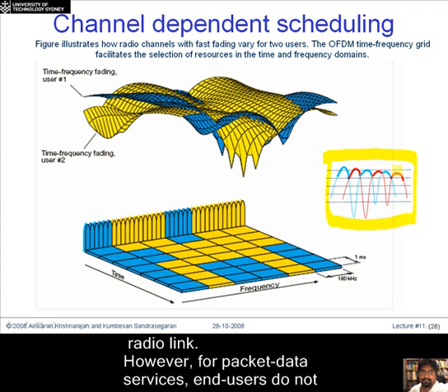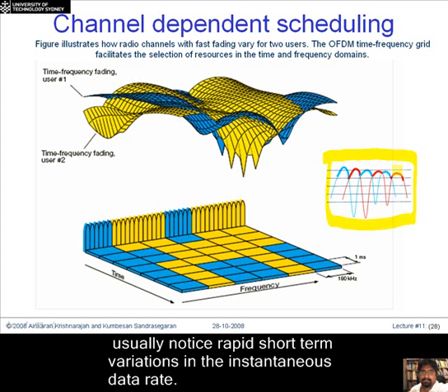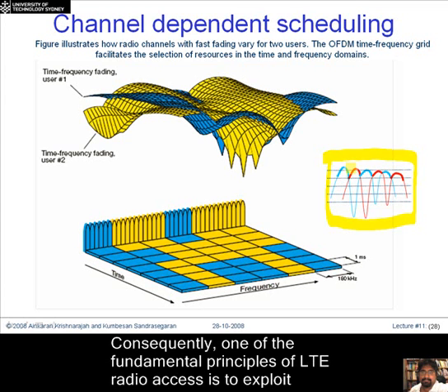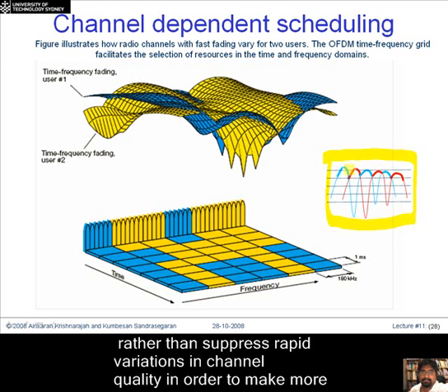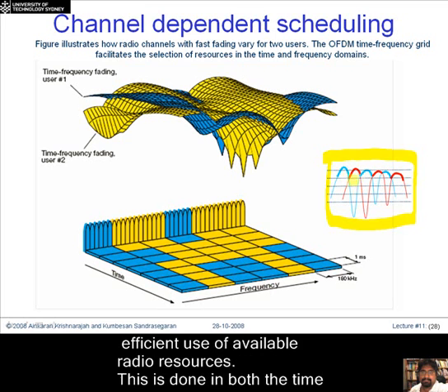Okay, now if this is the situation, if these are the measurements, then ideally what we want to do is, when the channel quality is good for any one user, you want to transmit as much data as possible for that particular user. So you can see that here the blue user transmits in the portion that is quite dark here, that represents the portion where the blue user is transmitting. Then the red user transmits because the red user's signal quality is better, and so forth.